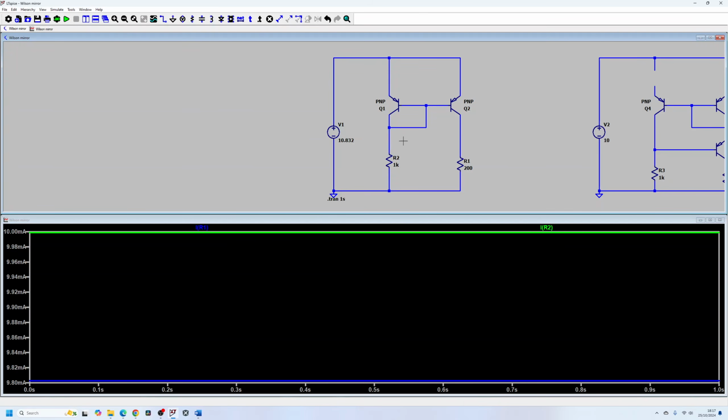So we have some current that we set over here because of our known voltage source and our known transistor characteristics. We set up a programming current and we got the same current flowing in a different path, basically because of our matched transistors. So you can see how useful this circuit can be, and obviously it's used a lot in biasing circuits, voltage regulators and things like that.